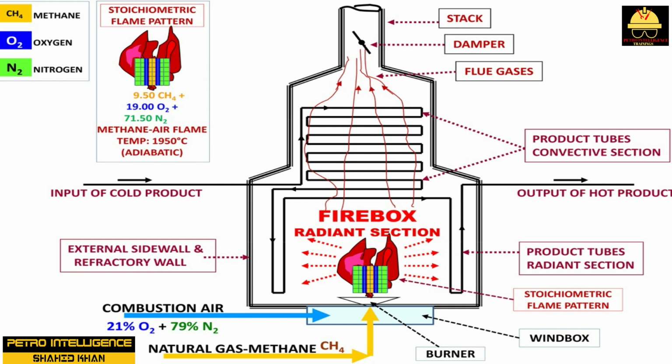Castables have a temperature range between 1,600 degrees Fahrenheit or 871.1 degrees Celsius and 3,300 degrees Fahrenheit or 1815.5 degrees Celsius. Typical heat loss from a furnace is between 2 and 3% of the total heat release. Since the insulation is porous, a protective coating may be applied to the inside of the steel shell to protect it from corrosive materials such as sulfur oxides.